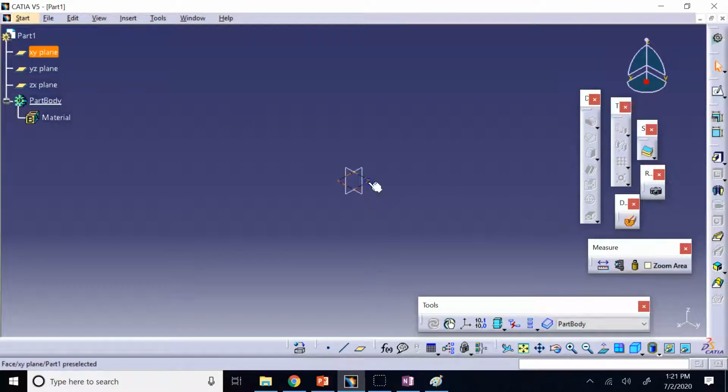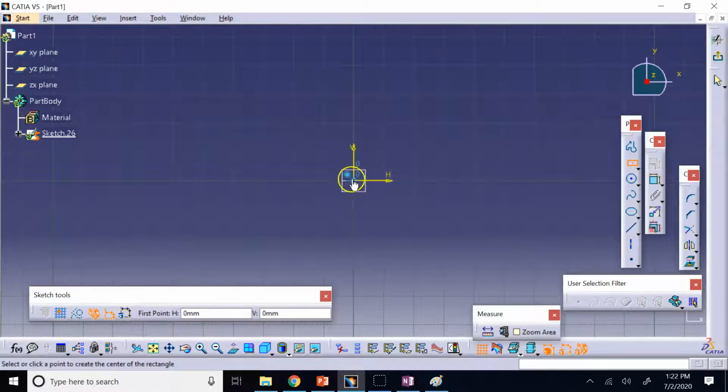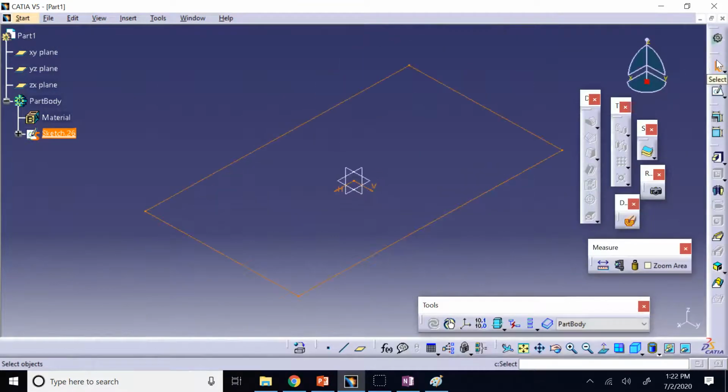Another option that you have is you just create the hole only, using, let's say, a cut extrude or even the hole command, and then apply the thread later on, although it doesn't have really any advantage. But if you have a part that you got from somebody else and imported it, then if you need to add a thread in the location of the hole, you can do it with this command.